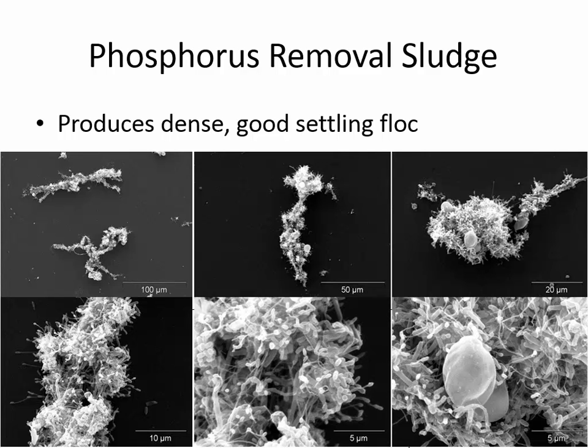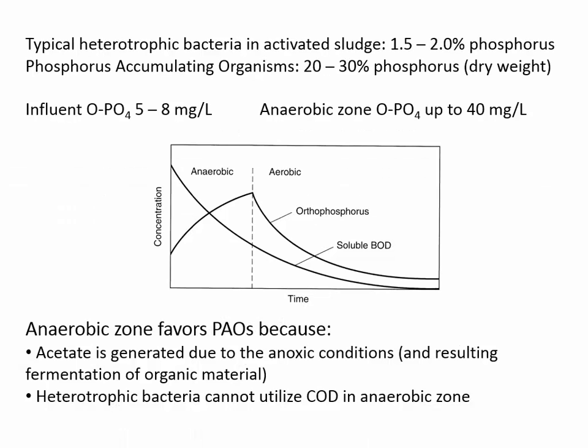So it doesn't have to be in the clarifier for very long. And that's fortunate, because if it was in the clarifier for very long, we'd be in trouble. Because remember, it'll start to go from polyphosphorus to orthophosphorus if it's not getting oxygen. So let's go back to this previous diagram. What happens in anaerobic conditions? In anaerobic conditions, it starts shedding its stored insoluble phosphorus into a soluble phosphorus.